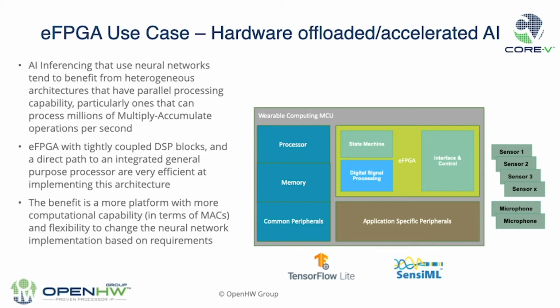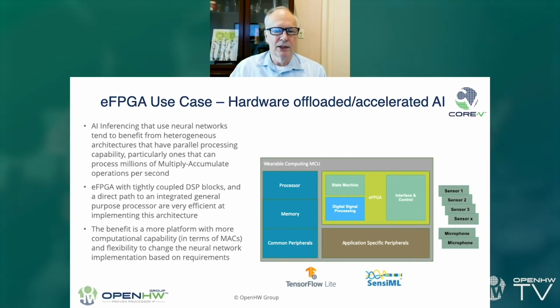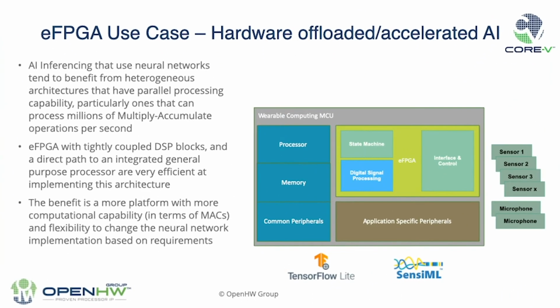So we take the things that are done very many times and put them in the eFPGA, and the things that are done only once are left in the RISC processor. By doing that, we can achieve something like either 5 times more performance out of the unit than we could out of the RISC-V on its own, or we can achieve the same performance at 1/5 the power, both of which could be very valuable in the IoT application space.